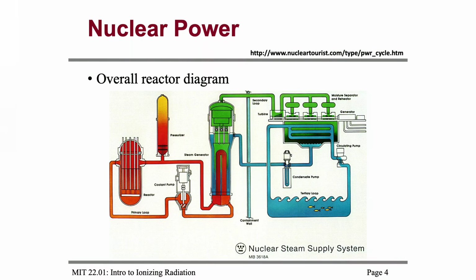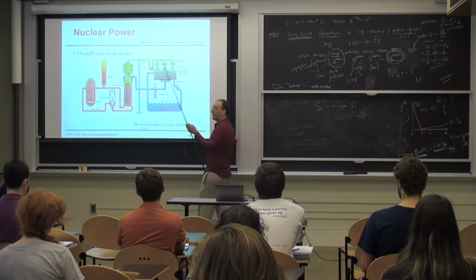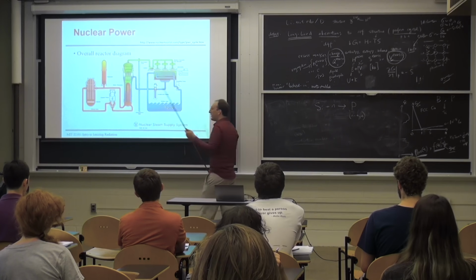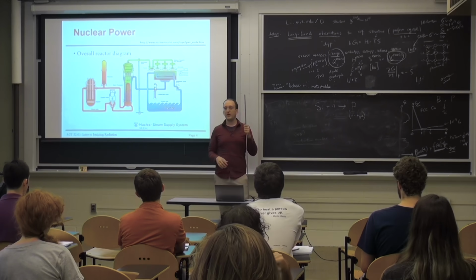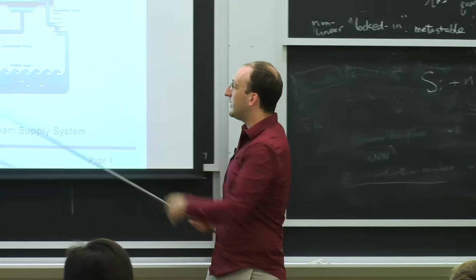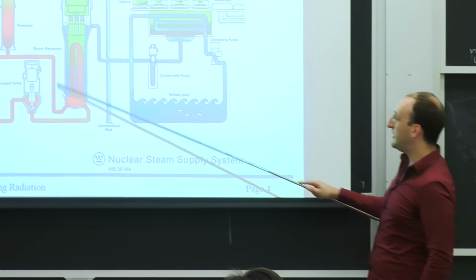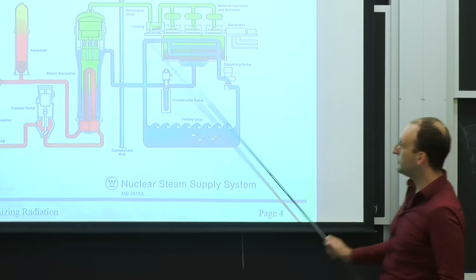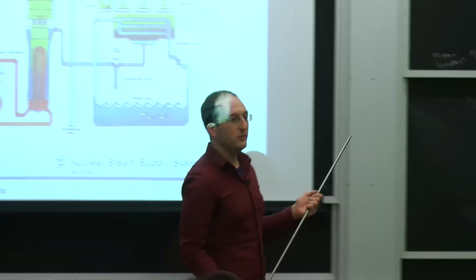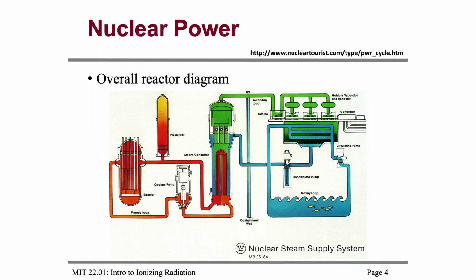First, nuclear power. The reason why I know a number of you guys are here is pretty simple. It's just a hot bucket of water. The way we make that bucket of water hot is by putting uranium or other fuel into these rods, assembling a lot of them in a small space, where they then heat up by producing nuclear fission, capturing the resultant kinetic energy of the fission products and neutrons and everything else that comes out, and using it to either heat up or boil water that's then just driven through a heat exchanger and a turbine. So aside from everything on this side, it looks basically like any other water-cooled power plant. The difference is things get toasty in a radioactive sense, but also pretty well under control.